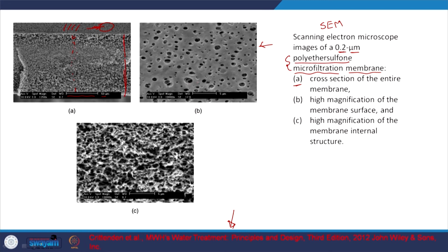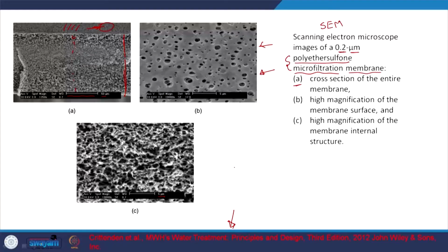Here you can see the pore size, and the particles are going to come here, particles meaning suspended particles in the water. You have pores of different sizes, but again you understand how it looks in the cross section. So, they are going to be removed by filtration. Here the primary mechanism is straining or screening. With respect to depth filtration, we looked at various aspects, sedimentation, flocculation, and such, but here it is usually only screening or straining. So, we looked at the cross section here in greater detail, and the surface. Again, you are talking about exclusion based on size.